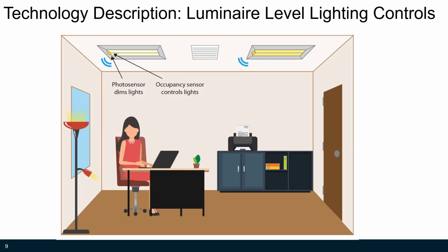We are beginning to see installation of a new market-ready technology, luminaire level lighting controls, which integrates sensors into each fixture. Not only can we automatically turn off lights in spaces when they are unoccupied, but the granular sensing array inherent in having a sensor in each fixture allows us to do this with confidence in much less time following actual vacancy.